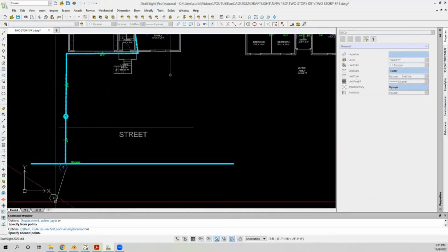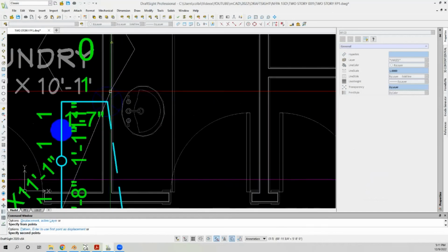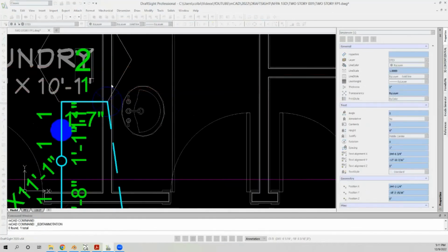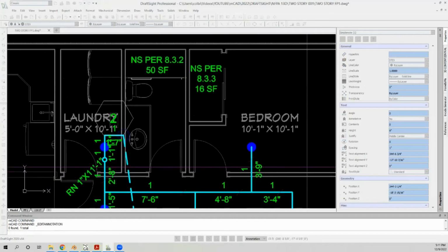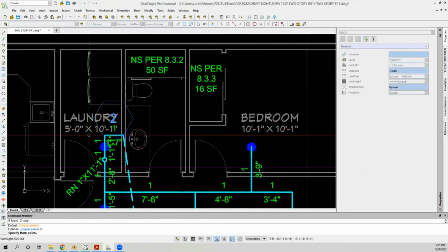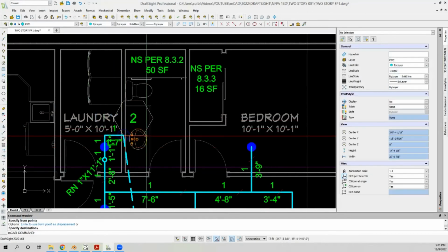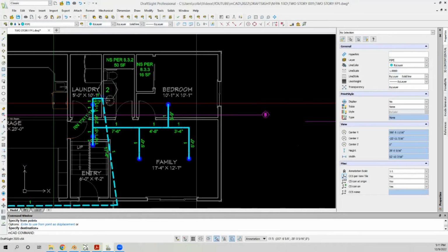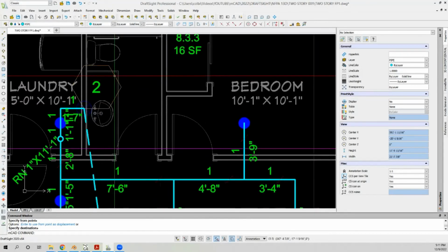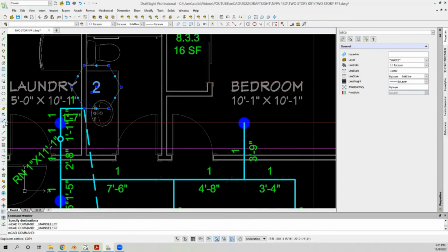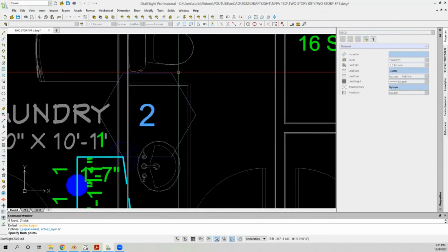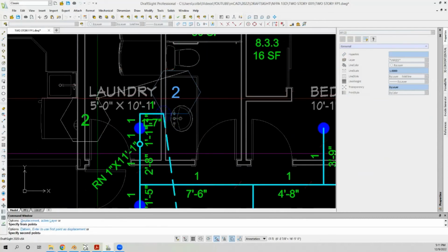I mean, on this plan, node 1 is there as well, but I'm just going to mark it as node 2 because this is a ceiling plan, theoretically, because we're drawing sprinklers. Okay, there's node 2. Now, it's totally not necessary, but I make a node for floor changes as well. It's just easier for me in my mind to keep the nodes straight.